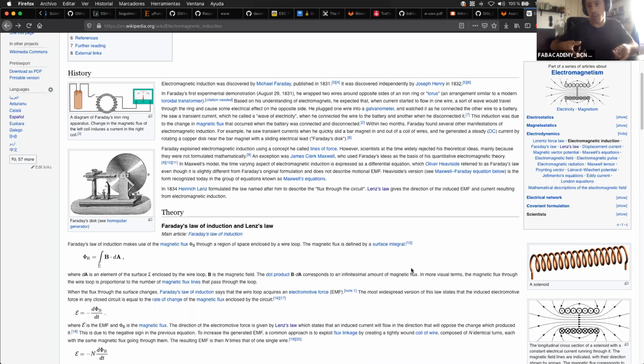The motors turn into generators for a second, and they give you back the electricity that you put in before to move the train. And with the inertia of the train, you can move the motors, and that generates electricity and puts it back into batteries, in the case that you have a car or an electric bus or something like that.